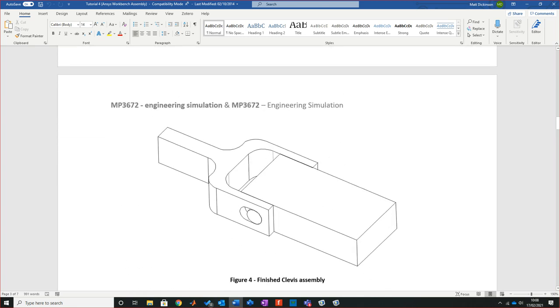We're going to hold this from the base area here, and then apply 1,000 pascals, not much, onto this face, and we're attempting to pull this apart. This is an assembly of 3 components: yoke, block, pin. Then we're going to look to see if it's given us something that we'd expect to see.